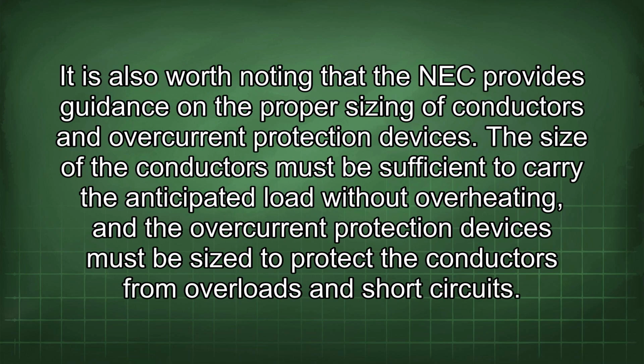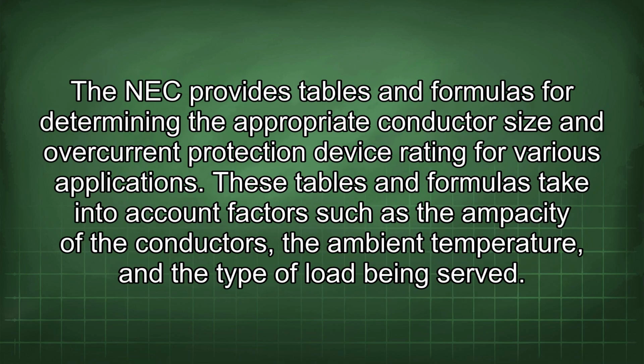It is also worth noting that the NEC provides guidance on the proper sizing of conductors and overcurrent protection devices. The size of the conductors must be sufficient to carry the anticipated load without overheating, and the overcurrent protection devices must be sized to protect the conductors from overloads and short circuits. The NEC provides tables and formulas for determining the appropriate conductor size and overcurrent protection device rating for various applications.